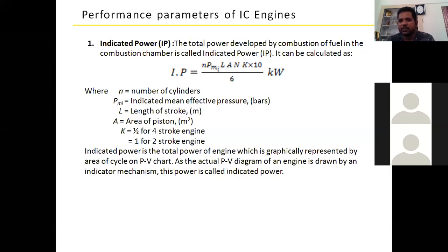That is something we call mechanical power, at the end of the shaft. Whatever power you measure by combustion of the fuel within the cylinder is called indicated power. The power of the combustion that happens in the cylinder is why we call it indicated power. It is indicated by considering the combustion of the fuel and air mixture.